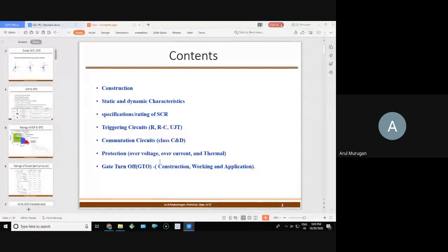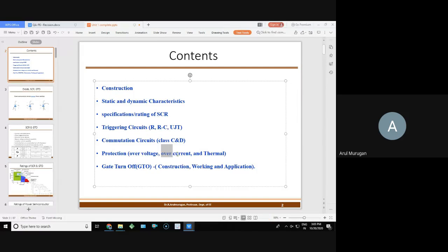The next one is over voltage and over current, which are produced due to stress. We studied the multi-level inverter recently. The purpose of the multi-level inverter is to reduce the voltage stress compared with the conventional inverter, where voltage stress is more. Why? Because the switches are on and off continuously. Due to that sudden on and off switching, over voltage and over current are produced.